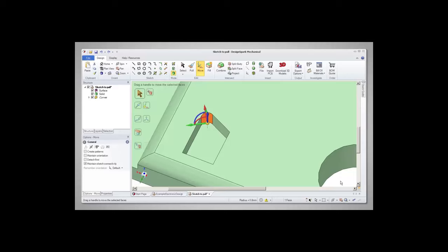It's very important to make sure the Move anchor is pointing the right way before carrying out the move. The anchor will set its direction perpendicular to the surface it is sitting on. Usually, this will be straightforward and in line with the geometry of the shape. With irregular shapes, like the rounded corner of the depression for example, any move made will not be parallel to the sides of the shape, but at 90 degrees to the point on the round.